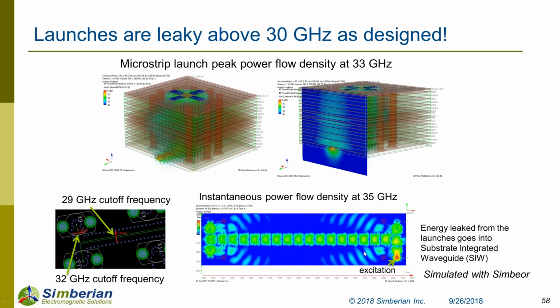Well, it depends. If you don't localize your vias, you're going to inject noise at even lower frequencies. Even for differential vias, you have some localization between the P and N in the via. But if you have common mode signals, due to skew or some asymmetry, that can mode convert and end up as differential noise. So for vias, provide the return paths really close to them. That's the best. Otherwise, you're going to run into problems.